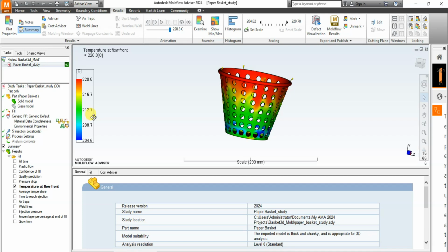Now let's see. It says also that you should try to change the following settings to improve the results using information in the table that you might have drafted. A table that might contain the problem. Let's say, for instance, temperature is low. The change might be to decrease the injection time. All right. Then the other thing that we're seeing here is possible problems may cause excess shear in the gate